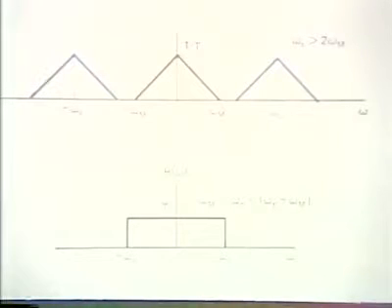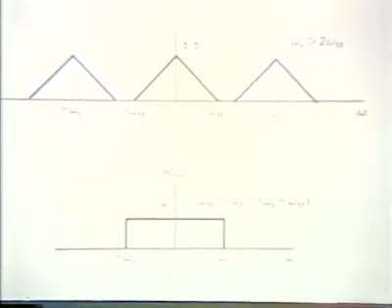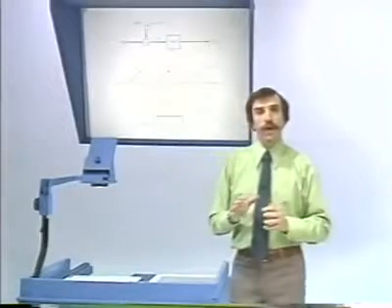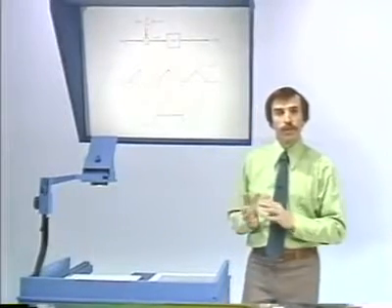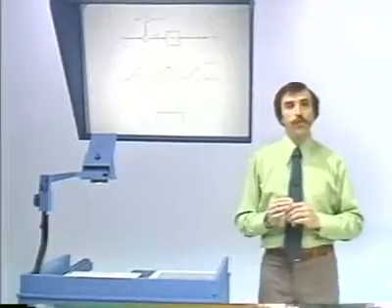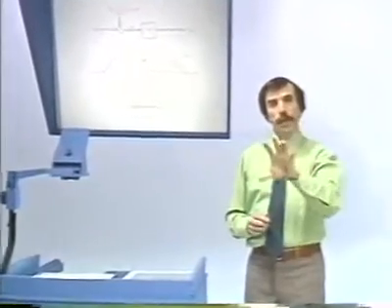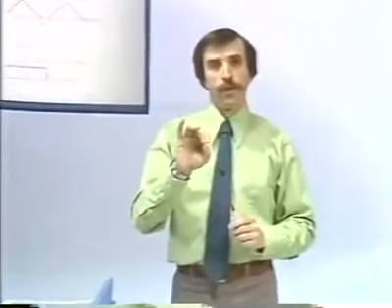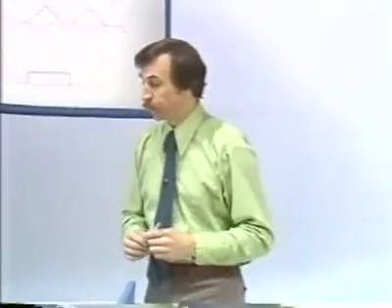Now, in this picture, an important point that I raised last time relates to the fact that in doing the reconstruction, what we've assumed is that in replicating these individual versions of the original signal, those replications don't overlap, and so by passing this through a low-pass filter, we can recover the original signal.